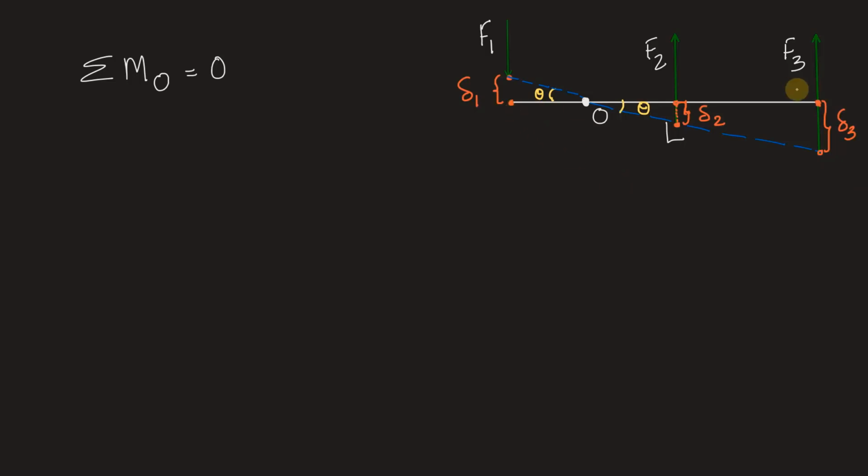Force on the bar due to its inertia will be m theta double dot. But the moment of this force will be computed by I theta double dot, that is moment of inertia into acceleration. So the first moment is I theta double dot, plus the second moment will be F1 into the distance from point O, that is F1 into L by 4, plus F2 into the distance, which is L by 4 again.